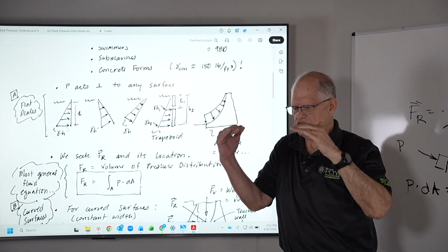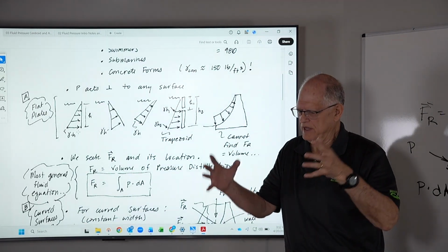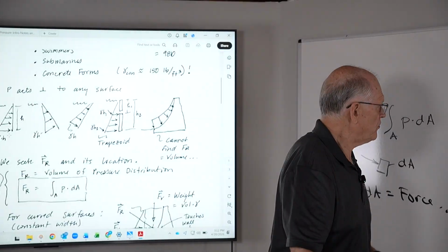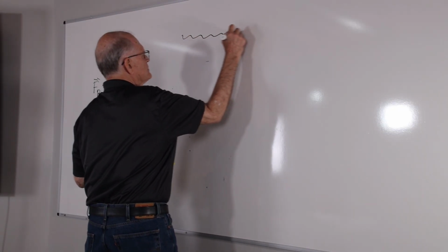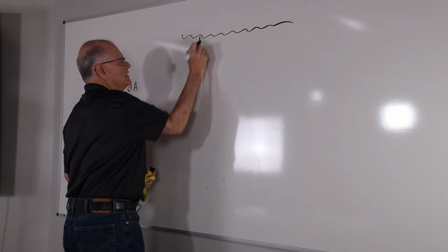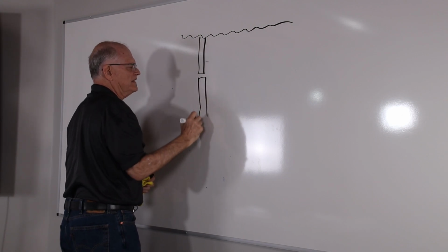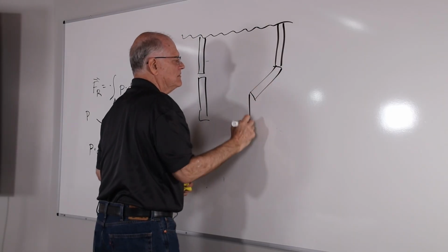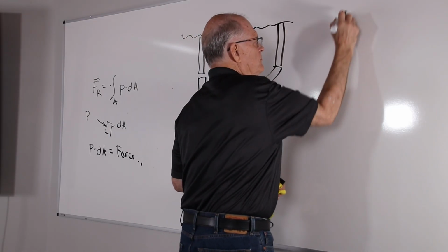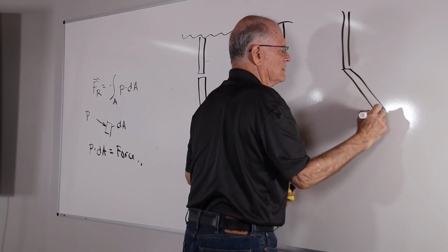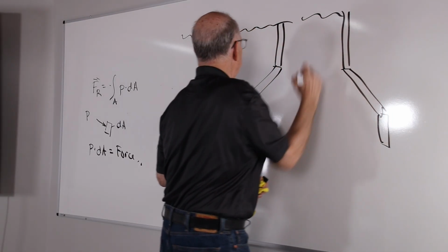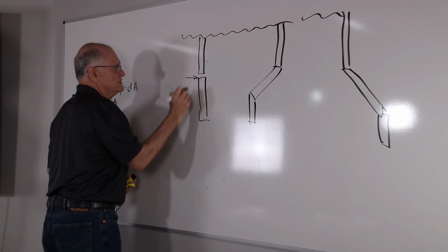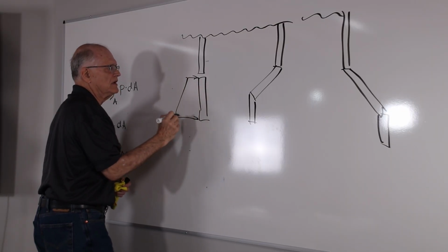And so anytime you have a straight plate, constant width, that's some depth, no matter what orientation, whether it's straight or whether it's... So if this is your free surface, and you have a vertical plate like this guy, or you have an angled plate, or you have a plate that goes back into the page this direction, again, your free surface is up there, then this is gamma h1, gamma h2.